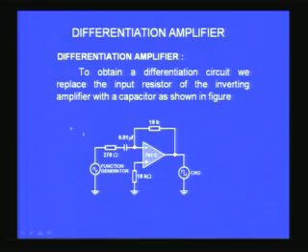To avoid that, I introduce a 270 ohms, so that whatever noise is generated at the input side will be dropped across the 270 ohms. The 270 ohms will make sure that not much voltage passes beyond this point, and therefore the noise currents will be very, very small, and they will have very little effect at the output, whereas because the value is so small, 270 ohms, it will not greatly affect the input signal which will be in the order of volts. So if I apply, then I will get that.